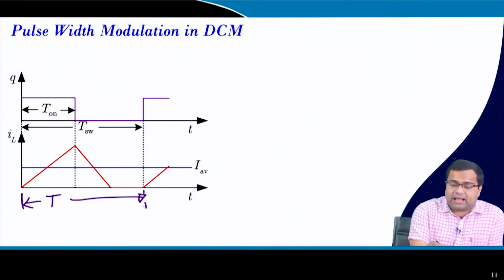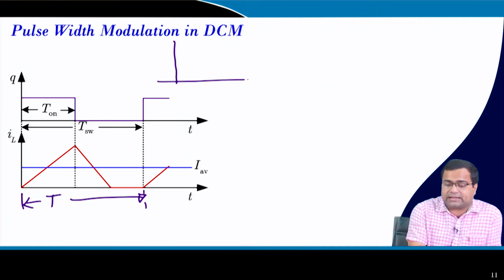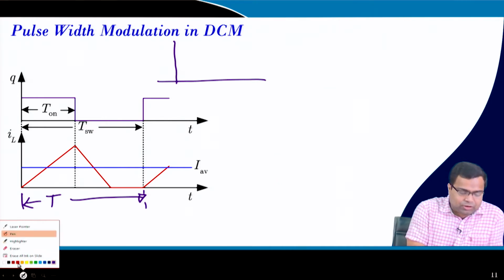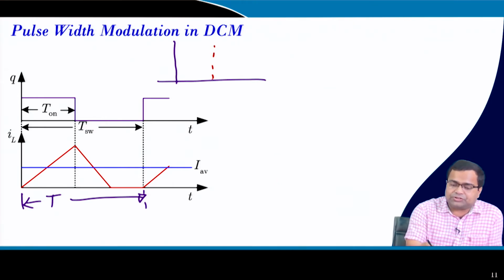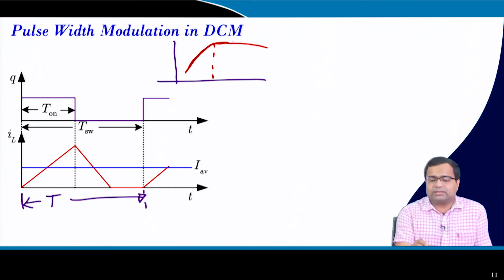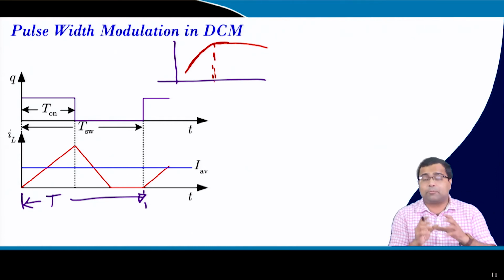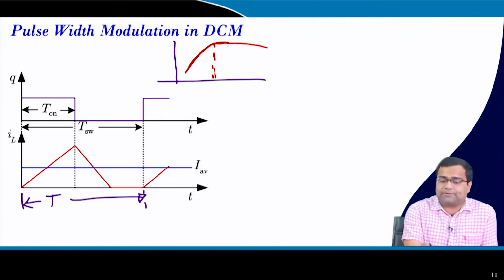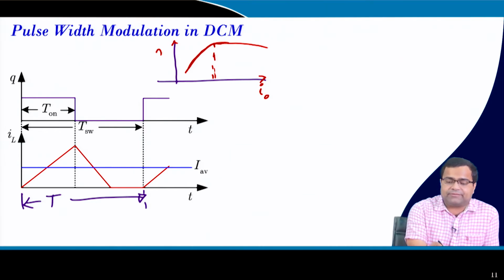Okay? And in fact, if you go through any product data sheet and draw it tentatively, suppose this is your nominal current, and nominal current can be high. You will generally find the efficiency curve like this, and here it falls drastically on this side. That means at some point you will get some optimal efficiency. This is with load current variation, and this is the efficiency plot.